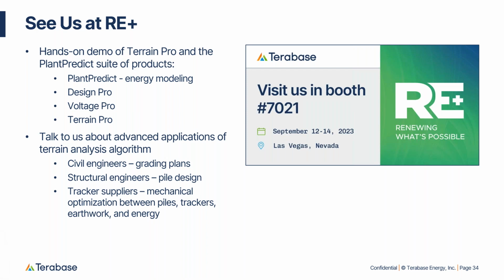Next question: does the output include an export for proposed contours? I'll take that one. The answer is yes. The output that can be downloaded in a CSV format includes the finished grade elevations at each pile, which you can import into software like Civil 3D to create a finished graded surface and generate contour lines from. So yes, it is possible to import the output of Terrain Pro into a CAD-based environment to understand both original grade and finished grade.